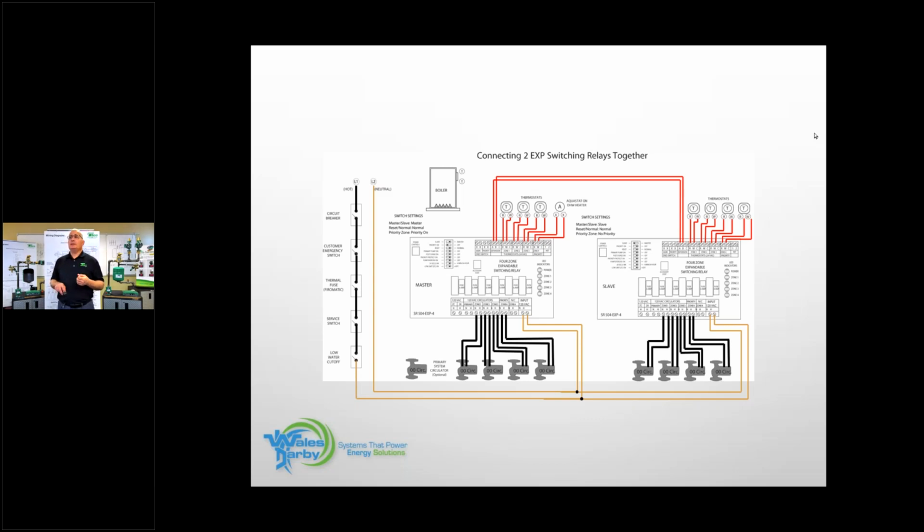We have our dip switches on there to make sure the system's got a priority zone if you want. Then we have our expansion port, the ABC, where A goes to A, B goes to B, C goes to C. Now the 2 panels talk to each other. And then my primary or master panel is the panel that's sending the signal to turn on the boiler from the main end switch, and also another end switch to tell this particular boiler, hey, high fire for domestic.